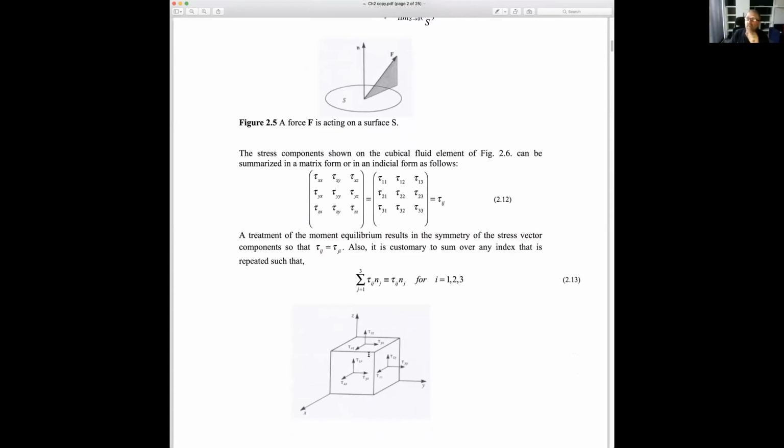So that's probably the best way to explain it with the little box. What are the forces in a box? Let's think that this is just a solid box, so we're talking mechanics now. What kind of forces can I apply? Let's say on the upper surface, and here's the coordinate system, the force direction is going to be, let's say, Z. So the normal to the surface is also Z. Therefore, the pressure we're going to call tau ZZ. You must have done the naming of those forces in other courses.